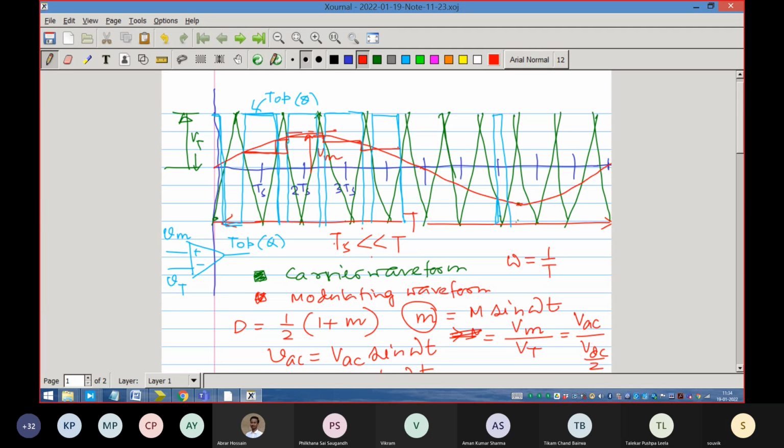But when we have to do low frequency, let us say even a 2 Hz sine wave, then you have to take a lot of samples in between. Otherwise you will be producing a waveform which has more harmonics. So this is a good practical question, and we make a compromise.